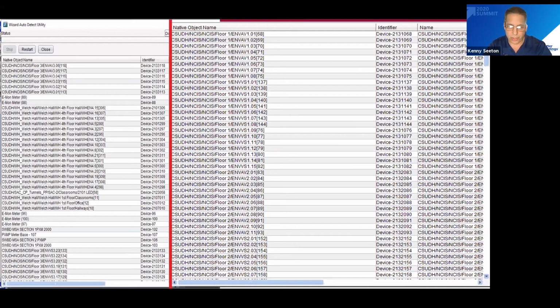So there's 2 screenshots here. The one on the left, they're the same. The one on the right is sorted, but depending on what building automation system you have, we use a Metasys at our campus, but all of the newer stuff should work. It's as simple as doing a device search. I'm not a control specialist, and I was able to figure this out.